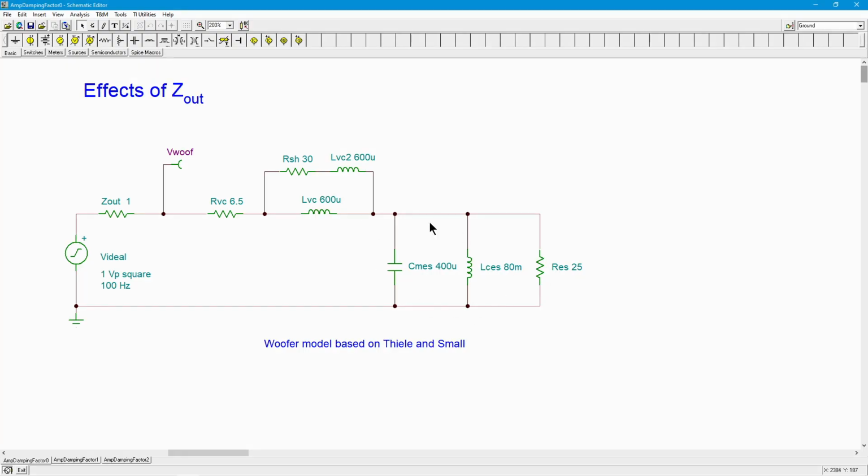This creates a parallel resonant circuit. The more mundane aspects are the resistance of the voice coil and the inductance of the voice coil. Those are sort of direct. But it might not be immediately apparent that part of this is a parallel resonant circuit. And what we know about a parallel resonant circuit is it has an impedance peak. It starts low, comes up to the resonant frequency, peaks the impedance, and then drops back down. And resonant circuits like to ring.